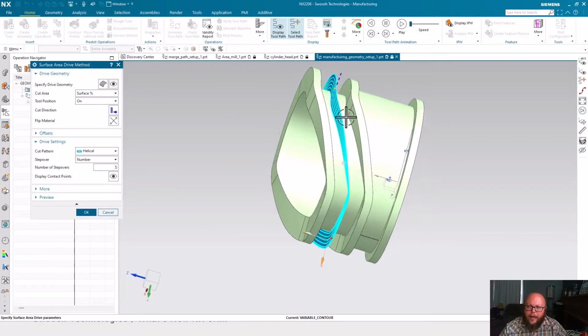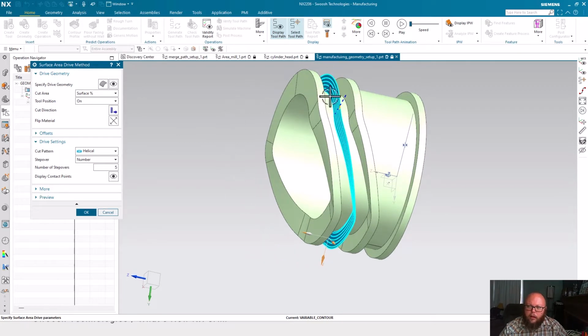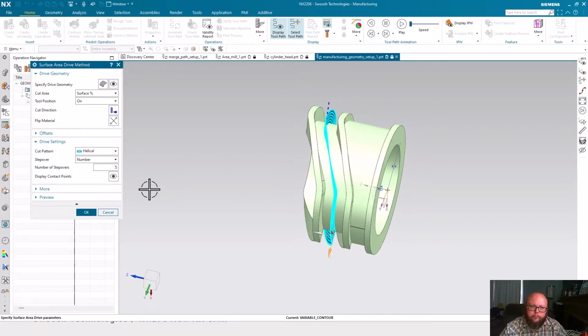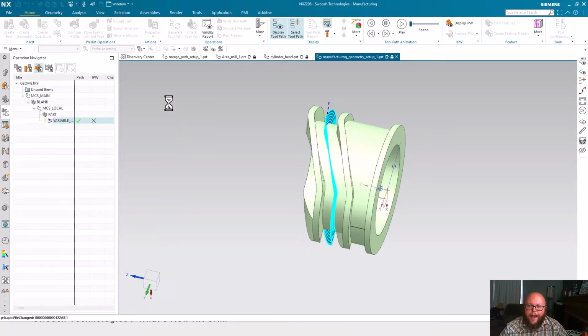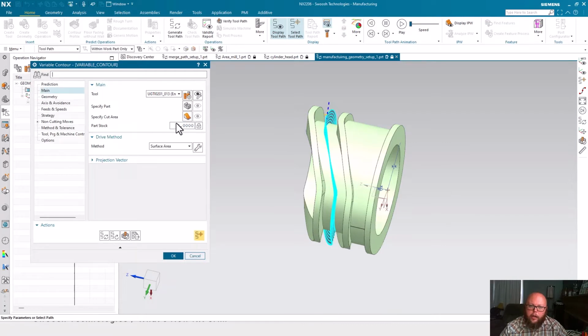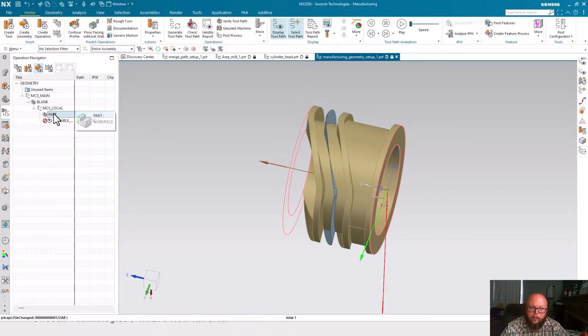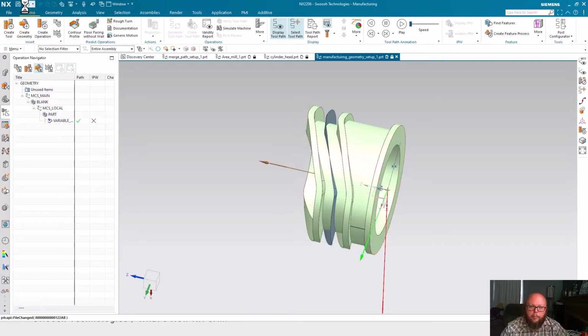And I've specified the tool position to on to have a nice helical cut pattern going down in a 4-axis type motion, essentially just slotting out this part geometry. So that's one use case, just the ability to not have part geometry and cut area specified. However, I can still inherit my blank geometry, and my IPW will update properly on down the line. That would not happen if I had my blank specified at this part level. I would not be able to have my IPW available to me at any time if I wanted to just review this individual operation. So that explains the reasoning why I like to divide those two up. I don't always use that, but it's nice to have that built into my template for when the time is right.